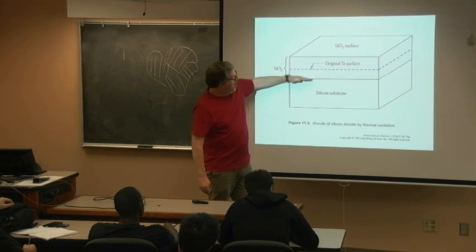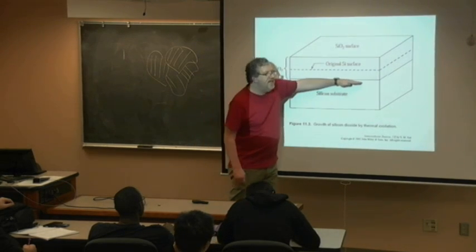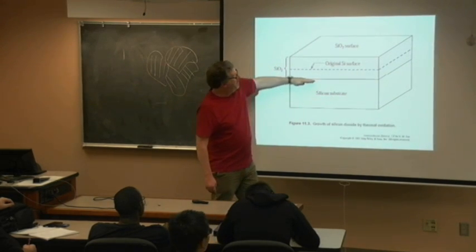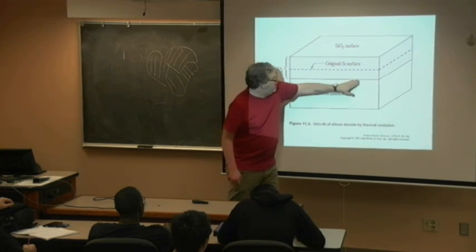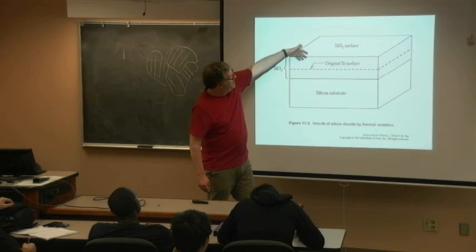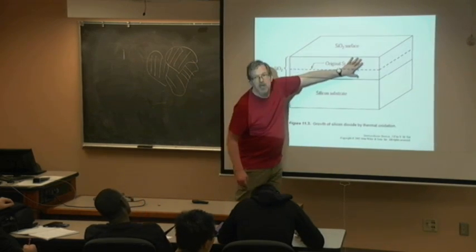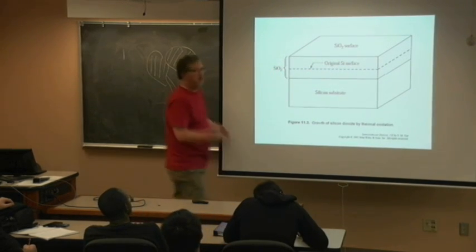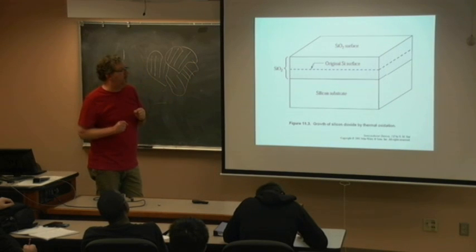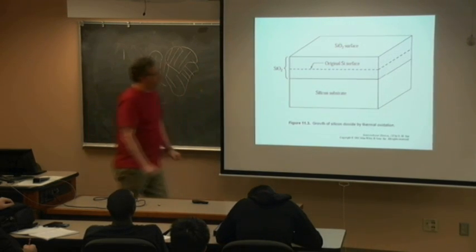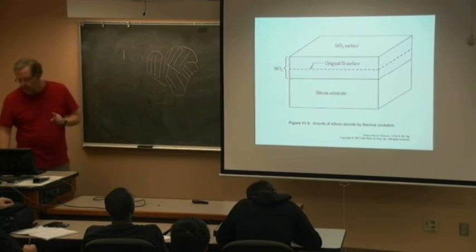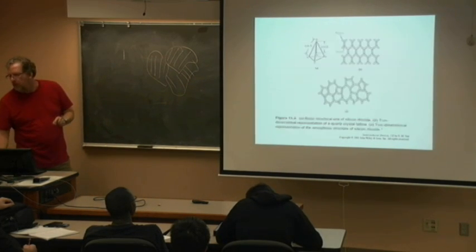And therefore, I'm leveraging a nice pristine silicon interface here that has never been exposed to ambient. So this is virgin silicon down here where this oxide has penetrated down. This is a high quality way to make this, the fact that it's oxidized from the outside in. That's the important takeaway point for this exam.